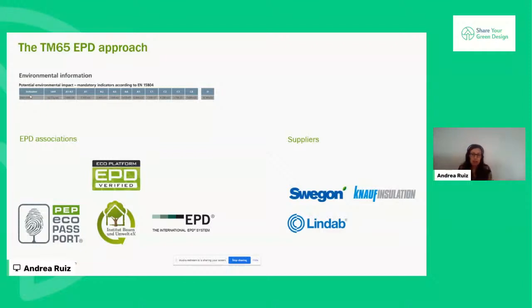The actual document is quite long, and we will need to identify the GWP of that specific product. The CIBSE guide not only helps us understand that EPDs can be used, but also to read the EPDs correctly and to define which values to associate with our basic or medium approach so we can sum them all together.